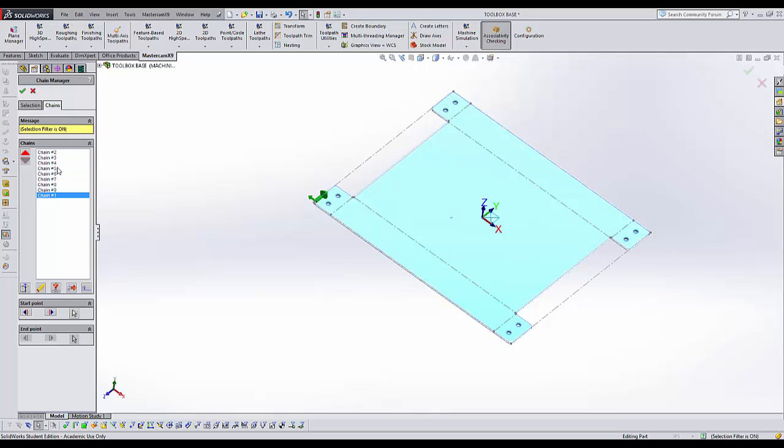So I can be more proactive in making my toolpath more efficient by choosing where I want to start. If I'm ending up here, I want my last circle here, then machine to there. So I want to start there. I want to find that one to be number one. As we go through, there it is, number one. I will move that to number one. And then number two would be that one there. So I need to move that into space two. Then that one should be moved down once. That one there, that one there.